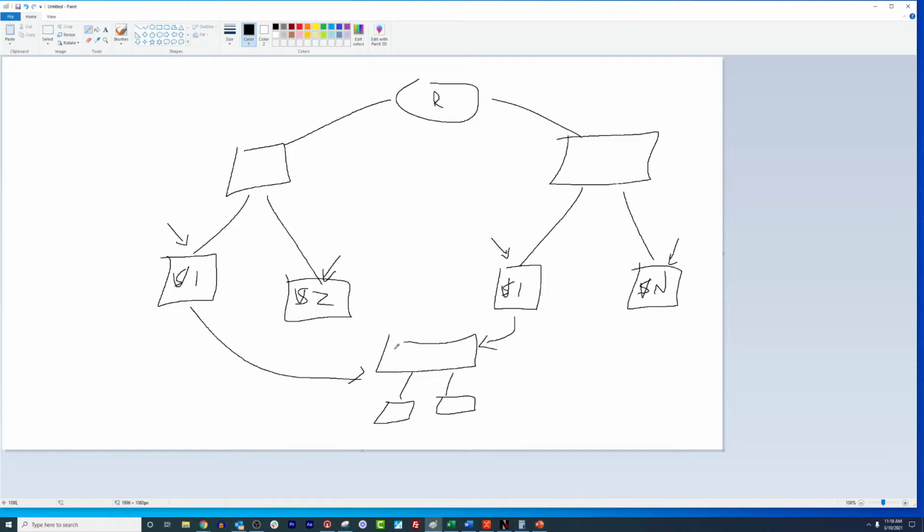Because if they're on the same LAN, then you don't need the BBMD to do the broadcast. Remember, there are only 2 services that you need the broadcast for: the Who-Is/I-Am and the Who-Has/I-Have.